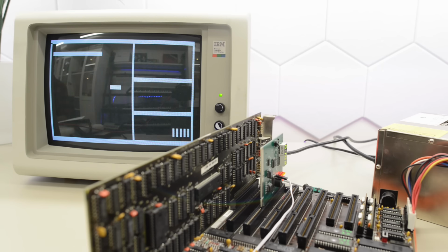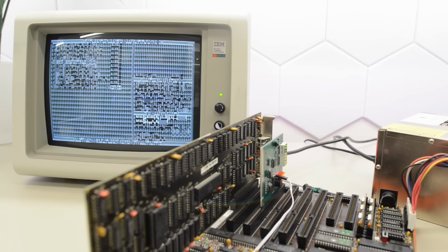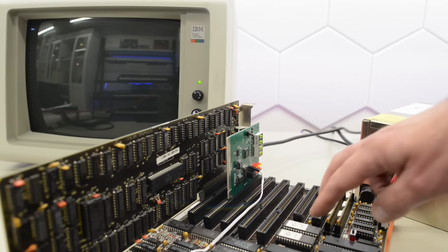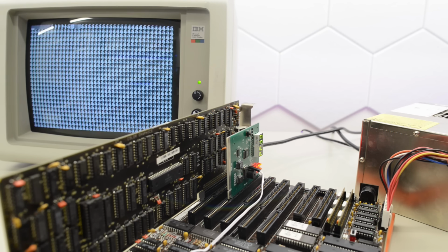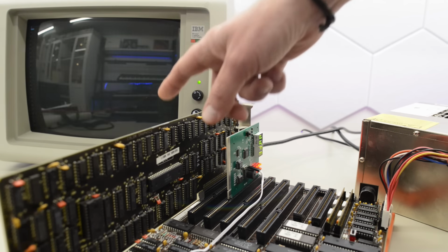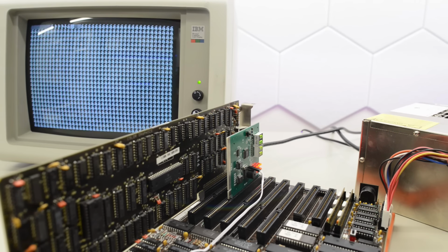So we've got some funny graphics, but these diagnostic ROMs only point to the same issue as we already know we have. Still those damn SIMs that are tested good. I decided to reinstall the original EPROMs, and now we're getting a flashing screen with characters. This probably isn't much of a clue, but it makes me wonder if that CGA card is okay. I haven't marked it, so I can't say for sure if it's tested.